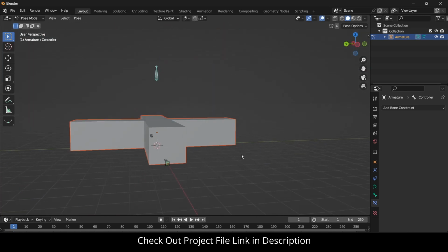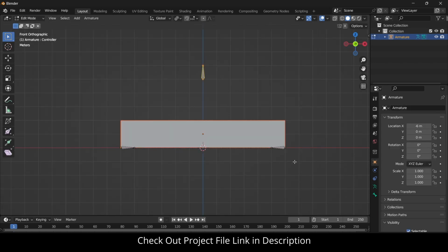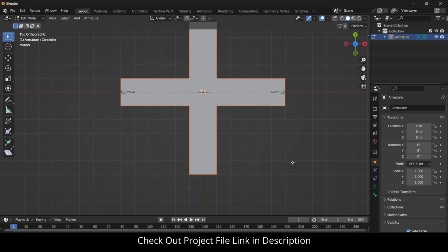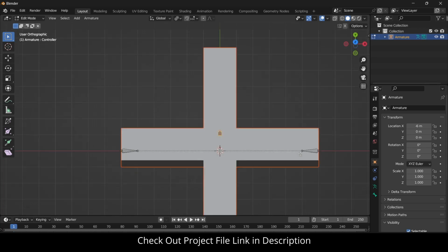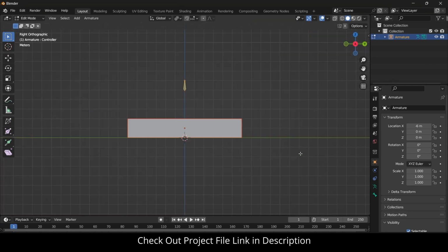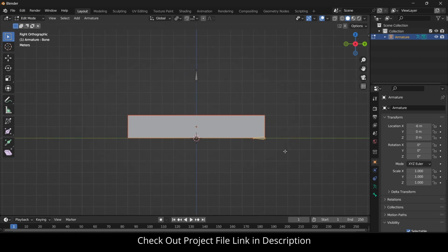Okay, now let's make two more. I will go to my edit mode. You can see these bones are already here, so I will look for a view where they are not. Okay, 3 is fine for me. I will click on Add Single Bone. I want to rotate along the Y-axis, minus 90 degrees. Press G, Y, 6. Select this, press Shift D, G, Y, 12.